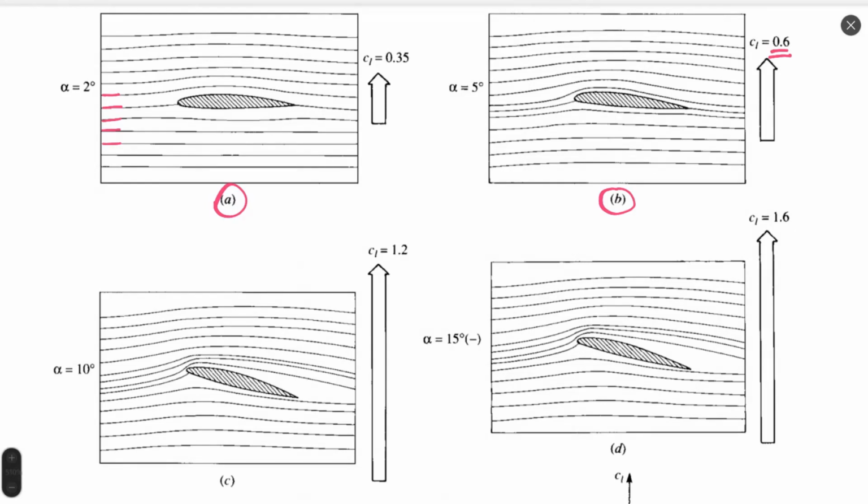I would like to remind you that the flow pattern directly reflects on lift, because the flow lines, or streamlines, we see visualized here can be directly converted to a velocity function, and then converted to a pressure function and lift coefficient as a function of pressure and pressure coefficient. So the visualization of these lines is not just the direction of flow. They have a more significant meaning, this psi function.